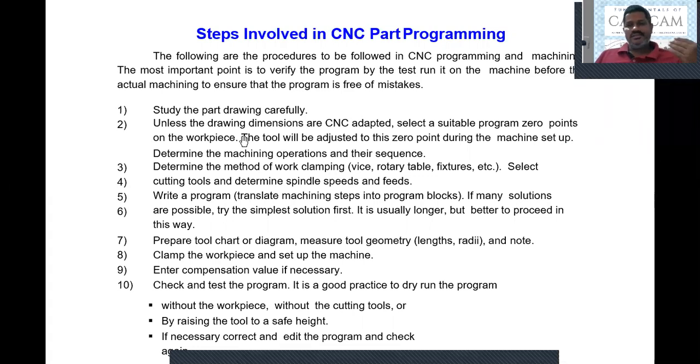This drawing can be a production drawing, or it can be a design drawing, any drawing generated from any of the 3D modeling software, which includes all the machining information. The first and foremost step in writing the CNC part program is that, once again, I emphasize, we need to read the component drawing very carefully.